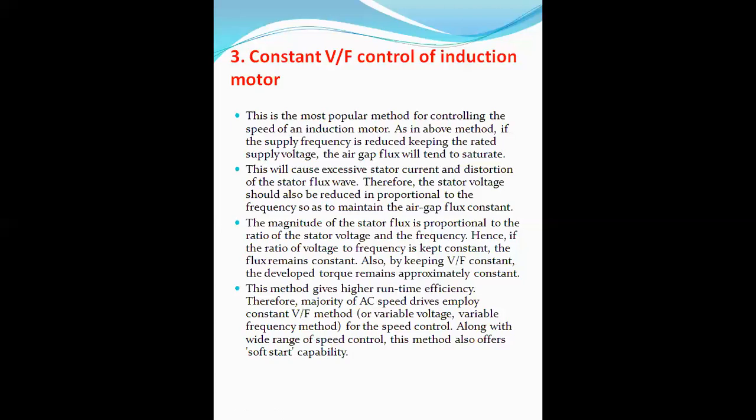Also, by keeping V by F constant, the developed torque remains approximately constant. This method gives higher runtime efficiency. Therefore, the majority of AC speed drives employ the constant V by F control, or variable voltage, variable frequency control method for speed control. Along with a wide range of speed control, this method also offers soft start capability. So this is the most important and commonly used method, known as V by F control of induction motor, to control the speed of an induction motor.